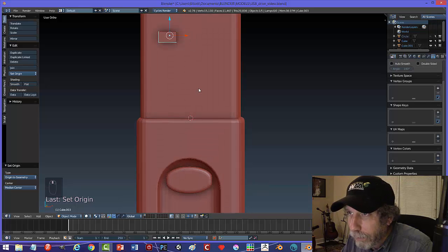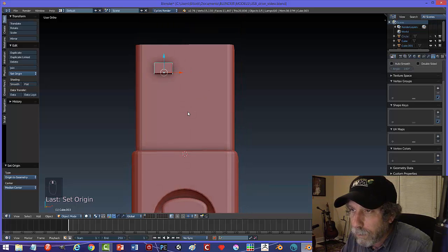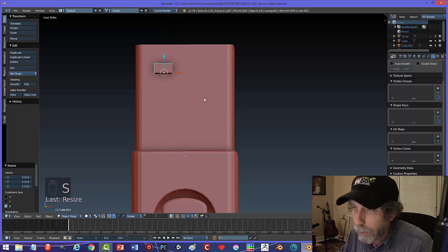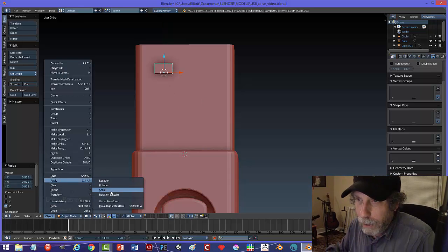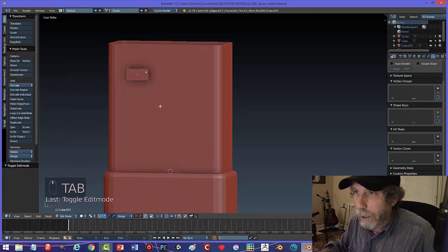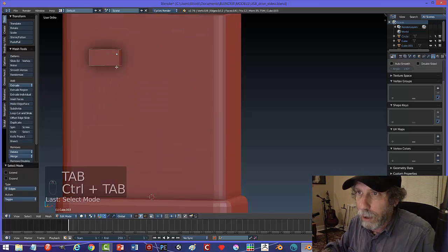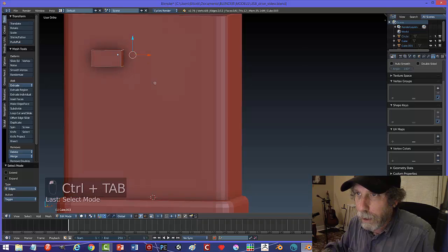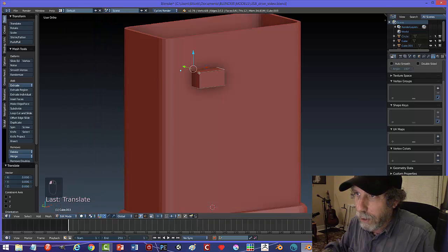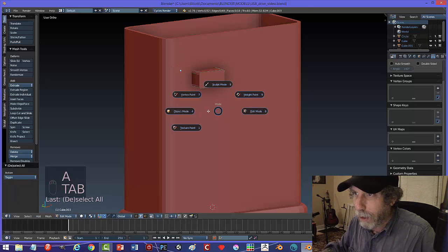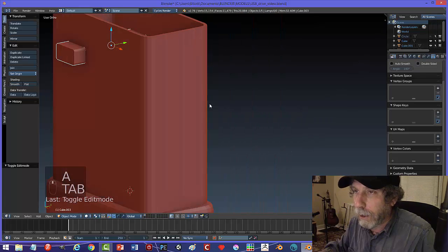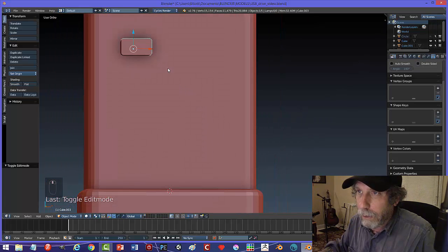And let's scale it a tiny bit more in the Z. Let's do an apply scale and round these corners off, or these edges. Select all 4 edges, Control B, pull on my mouse, add a few segments, and now it's rounded. Beautiful.